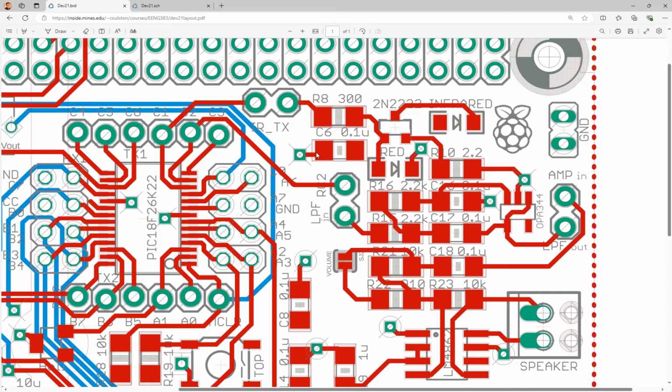So where do we want to probe? Just look at the PWM. RC1, here. It's connected, just probe it without a jumper. If you connect a jumper to it, what's going to happen? You turn on the IR. Why is that bad? It could hurt your eyes. Yeah, sometimes you forget that, you don't pay attention to it. You're looking at the wires and trying to figure that out, staring at it. That could be bad, right? So you don't have to always keep the jumper on the top, unless you really need to test the IR signal and receiver, that kind of path, which is at the end of lab 6, actually.